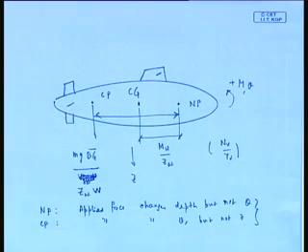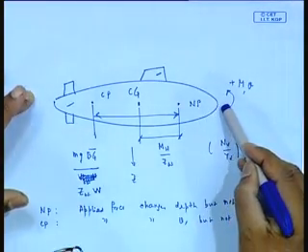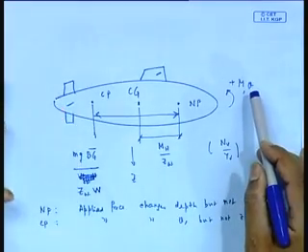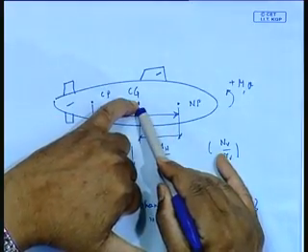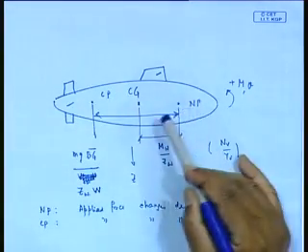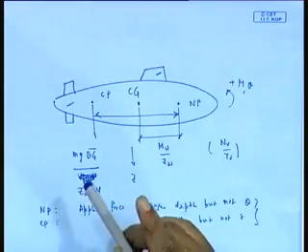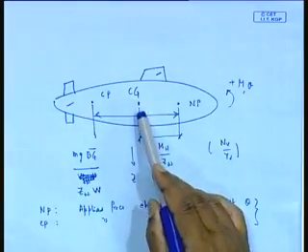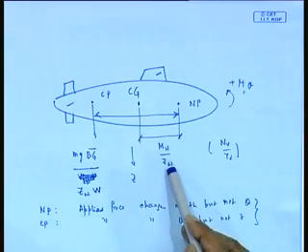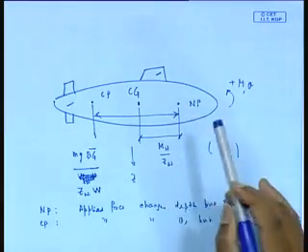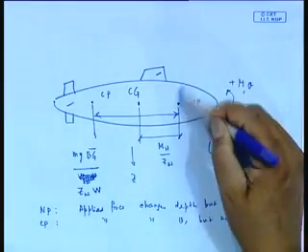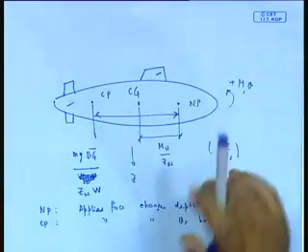Okay, now we are in a position to discuss. There is a submarine here, and there is a center of gravity somewhere here. There is a point called the neutral point, which is the same as what we called the neutral point for a ship. The distance of that neutral point from here is mw by zw. These are the two coefficients. What is the neutral point? The neutral point is the point where if you apply a force, it will change depth but not trim angle.